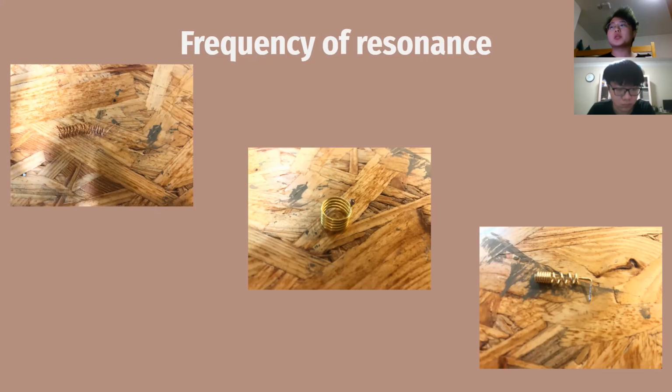In the experiments with the circuit, we tried placing different types of antennas to jam different types of signals, which are the 3G antenna, the 433 megahertz antenna, and the handmade antenna with 24 AWG wire with 15 turns. But after we soldered the three different types of antenna to the PCB board, it didn't work either. So for the first step, we will change the materials, the turns, and the length of the antenna to discover what's going on. And hopefully our project will be successful somehow.